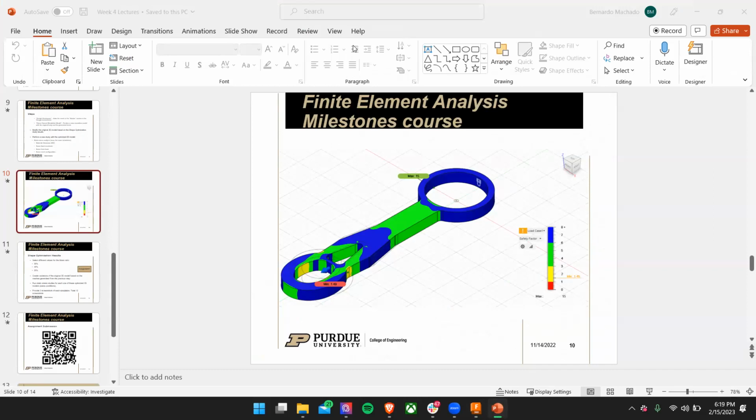You can do it multiple times if you feel that the part has too high of a safety factor after you use shape optimization, or you could simply go back and change that mass factor that's left over to something lower than what you had previously.